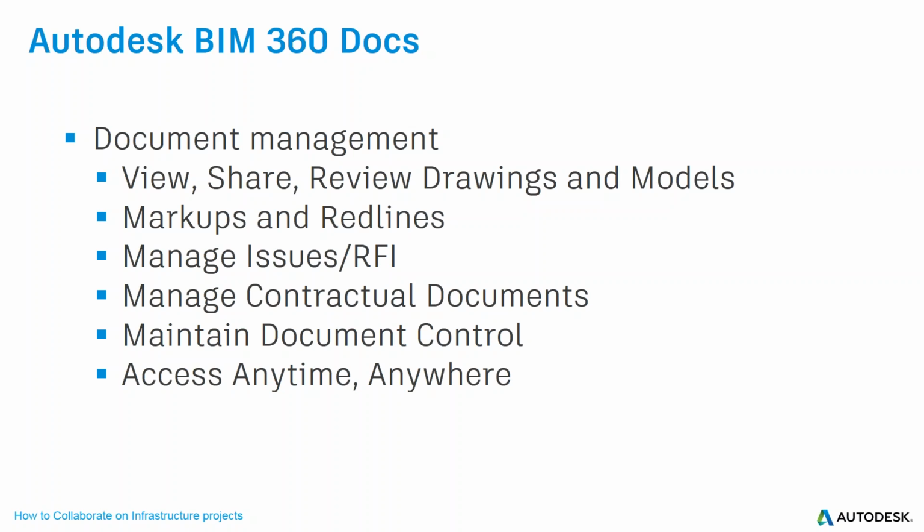So basically to put here something which I would like to know more about. And we also have what we call issues and requests for information, RFI. So an issue is something which you want to address to somebody. Okay, here I see some problem on the model, and the system is automatically sending a message to somebody whom you assign to this issue.